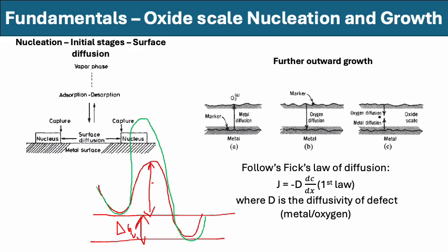This is the activation barrier. This activation barrier for forming this red oxide is lower than for the green oxide. So which means the nucleus of the oxide that might form on the surface initially is more likely to be the red oxide rather than green oxide, even though both red and green oxide have the same driving force for formation. So that we need to keep every time in mind. So nucleation has an activation barrier, so that must be kept in mind.